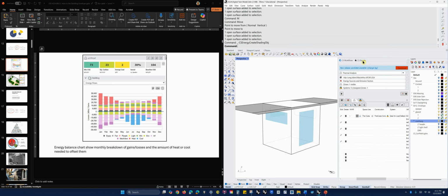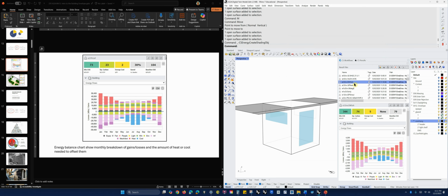And I did that, and let me just show you the results. Now I'm going to compare. I'm comparing it to this, which has the same window setup, and there's no shading. So let me turn off the shading just to be clear. So I went from 378 to, oh no, actually I'm comparing it to this glazing placement. This is the same glazing. And then if I change the infiltration, I almost cut it in half. It's a drastic difference because that's a big chunk of the losses. It was mostly losses in the winter.